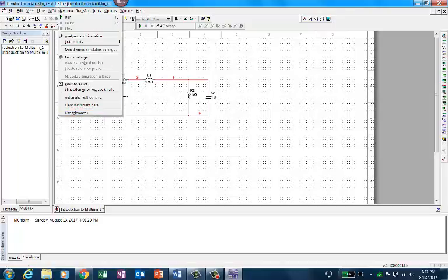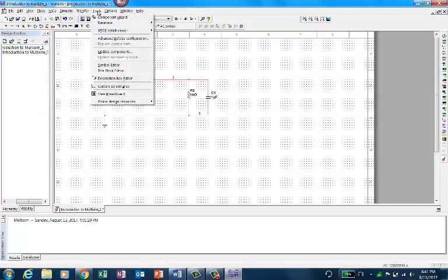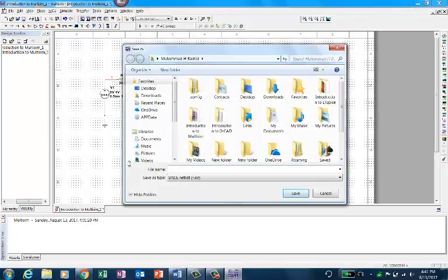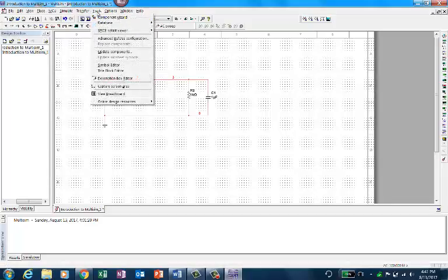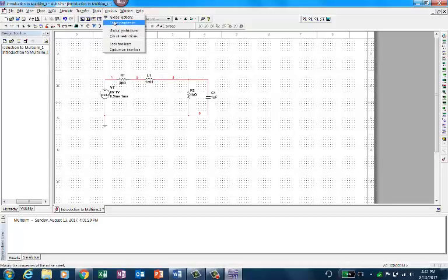You need to get to the tools, like the net view, the SPICE netlist. If you create a netlist between one software and another, it will basically say that R1 is connected between net 1 and 2, it has a value of 20 ohms, and L is the inductor connected between node 2 and 3, with 1 millihenry, and so on. So I'm going to see whether the option you have is sheet properties.